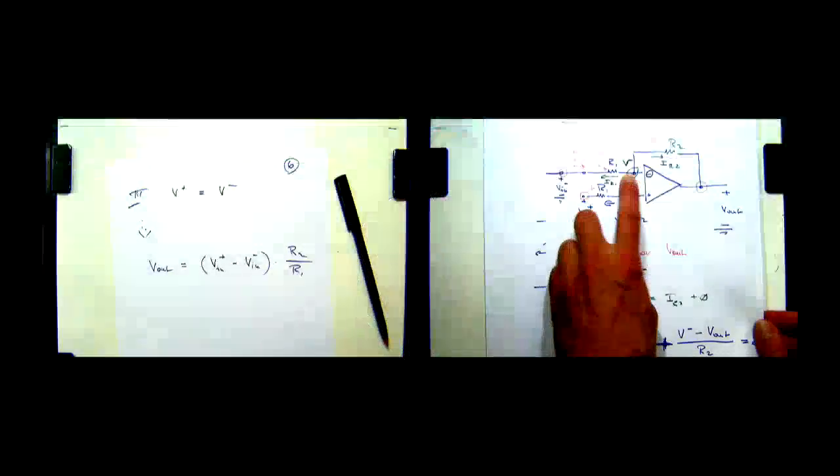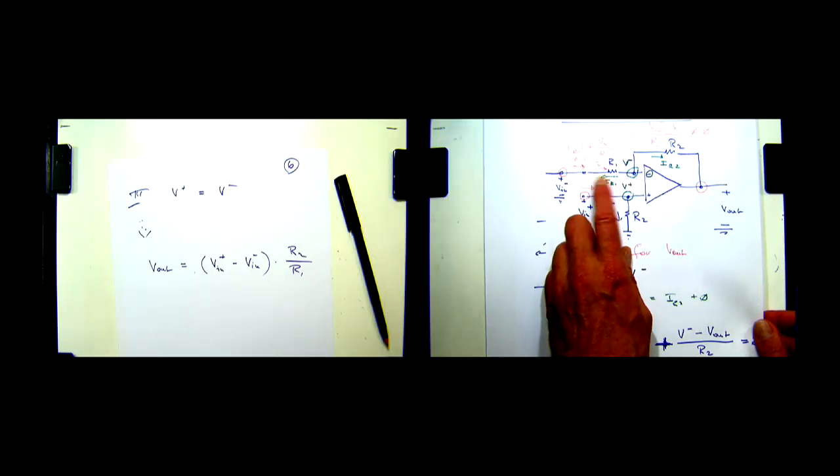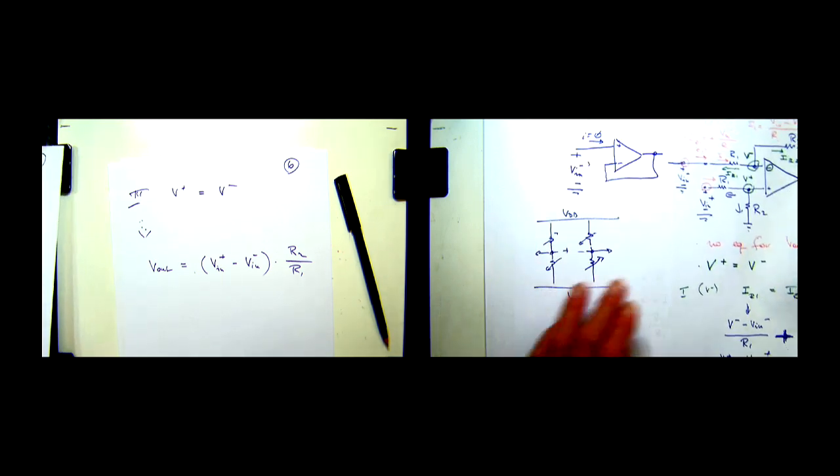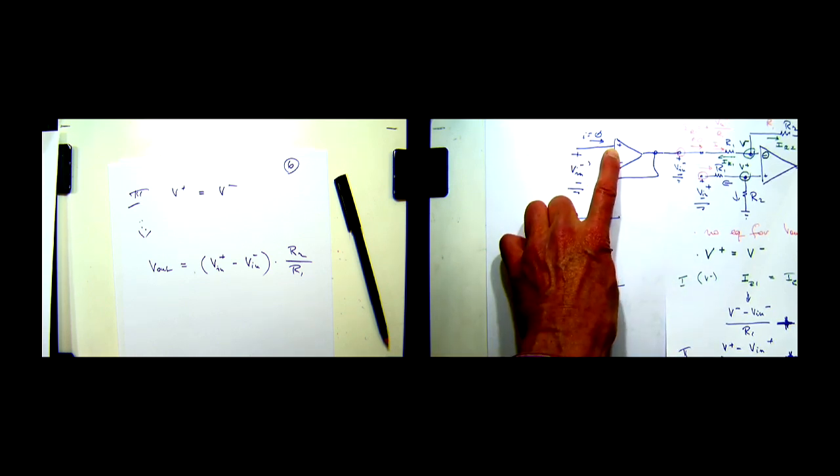Precisely. So the question is, the op-amp does a little bit like the voltmeter. It measures what it's supposed to measure, but it doesn't affect the circuit. Right, so that's absolutely true. It does not affect the circuit because there is no current flowing in. But the minute you apply other elements around the op-amp like this R1 here, you've got to be careful. Now it's no longer true. But you can fix it by just using another op-amp here, where you don't have any of these resistors. And now the current is going to be 0 there.